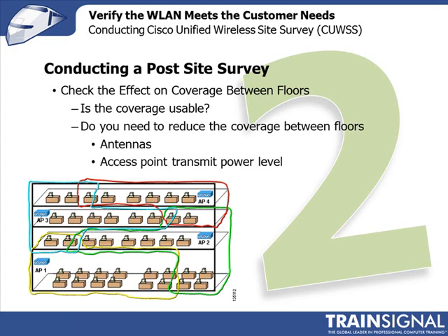I've personally found this is very true when you're using omni antennas on the ceiling, that you'll get this spillover depending on the material that makes up the ceiling. And from experience, I've found that the patch antenna tends to propagate through the floors not as well as the omni antenna, although you still want to measure it just in case it's causing some co-channel interference between floors.